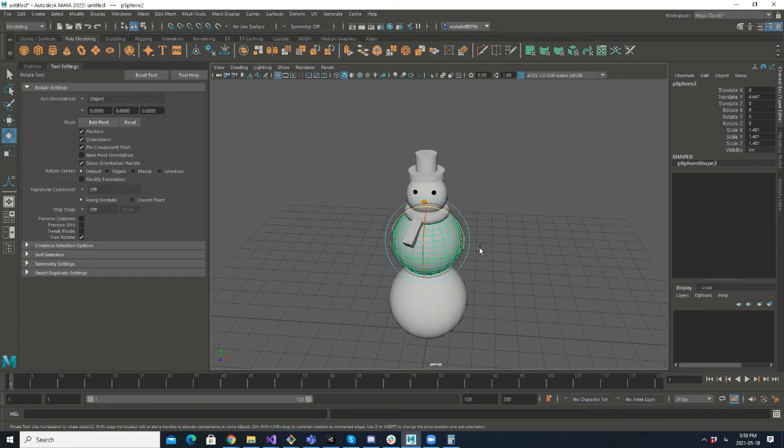If you want to rotate your objects not along the center of, let's say, a sphere, you can edit the pivot. You can, for example, move it here and then now try to rotate it. You can see that it rotates along that point that I mentioned. Sorry, not using shift. Sorry. Yeah, and you can see that it just rotates along the point I wanted. So this tool setting is going to be used in the future, but it's not really important for today's lab.